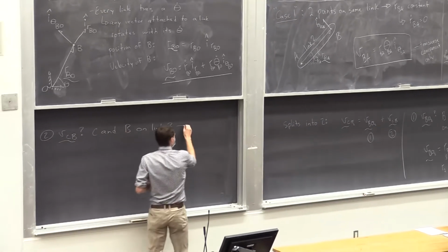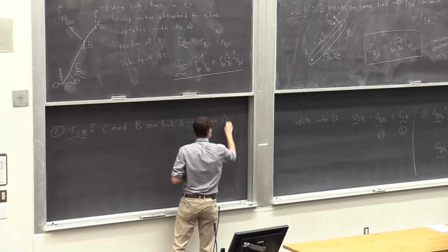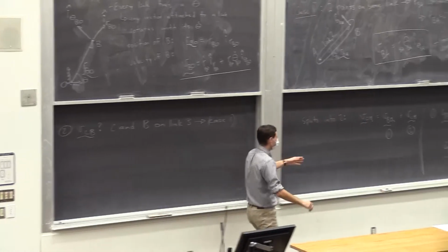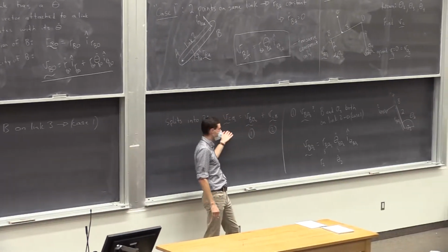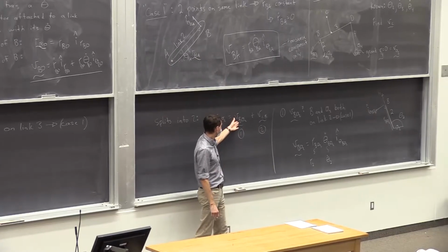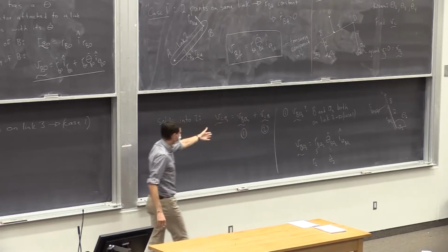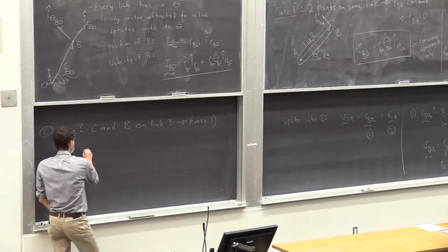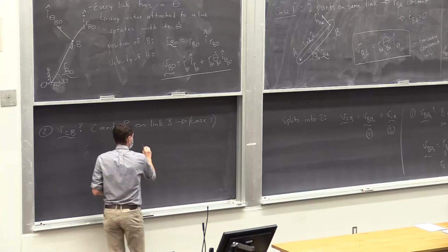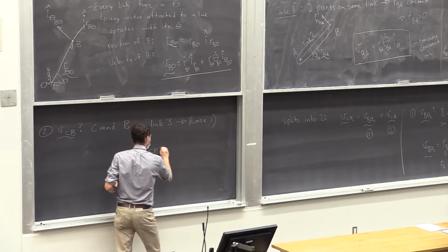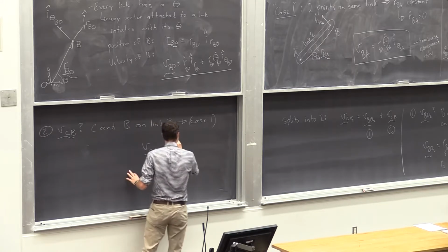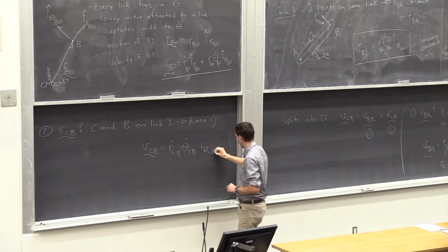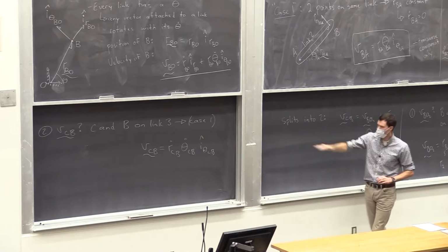And this, of course, is another case 1. So that's great. We love these case 1s. We're always going to try and build up. But you have the choice of how to design this analysis. I chose to start at O2, go to B, and then C. And I chose that because it led to 2 case 1s. So here's another case 1. So we can write that immediately. Let me put it over here.